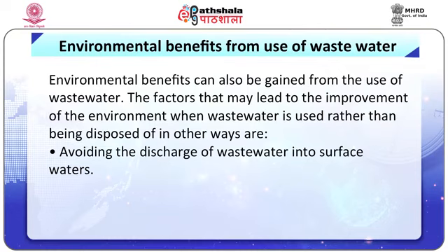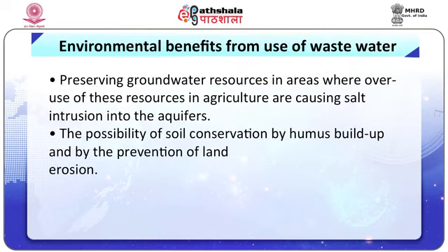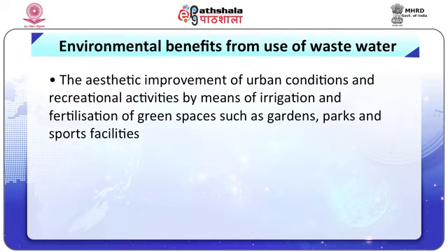Environmental benefits from use of wastewater. Wastewater reuse has environmental benefits. The factors that may lead to the improvement of the environment when wastewater is used rather than being disposed of in other ways are avoiding the discharge of wastewater into surface waters, preserving groundwater resources in areas where overuse of these resources in agriculture is causing salt intrusion into the aquifers, the possibility of soil conservation by humus buildup and by the preservation of land erosion, and the aesthetic improvement of urban conditions and recreational activities by means of irrigation and fertilization of green spaces such as gardens, parks and sports facilities.